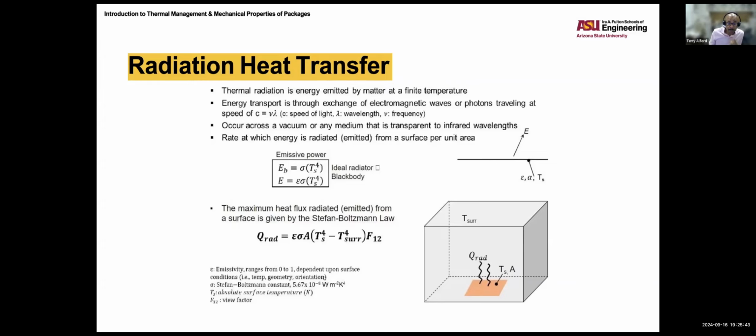Now, if I look at the case of C4 solder balls, now the die is exposed. So I get a lot more convection, still get a little radiation, and I still get conduction through the traces.